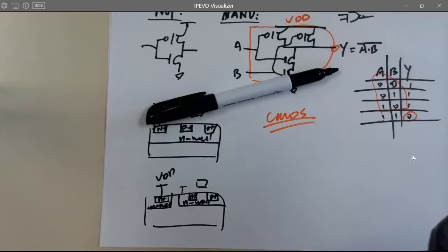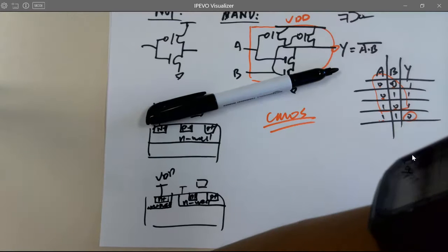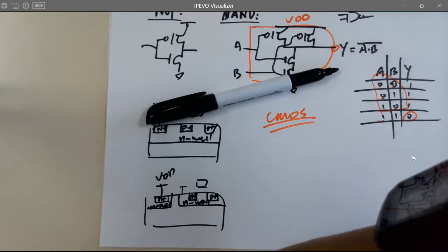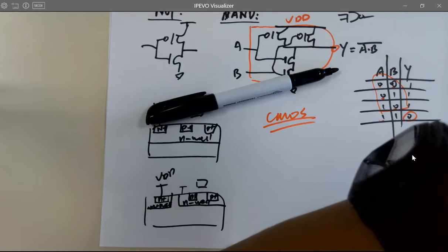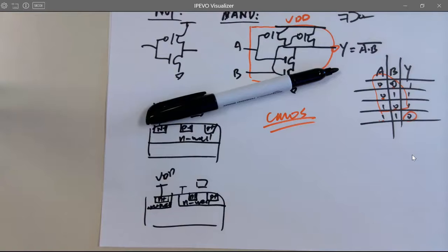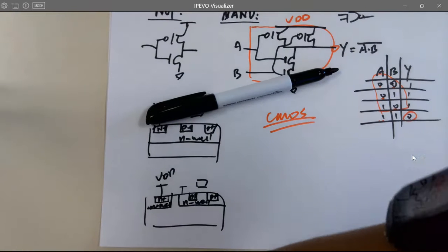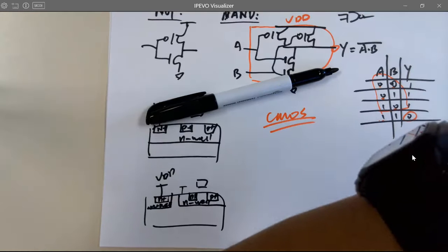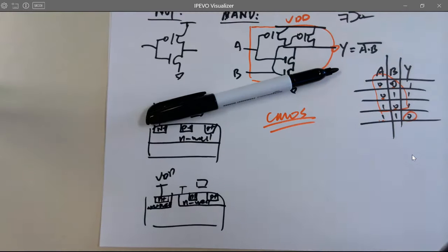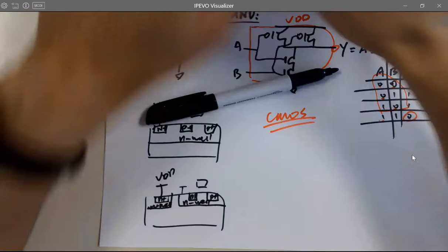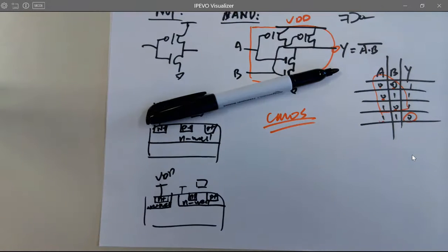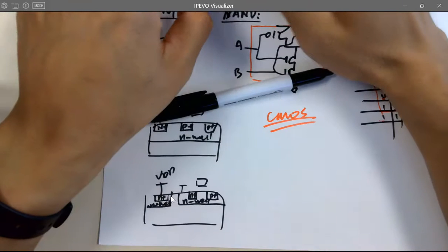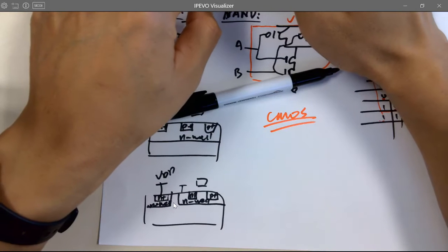The smallest size they can fabricate is 500, for example. And the size between the two wells is like only 1 nanometer. It won't pass, right? Because the tool or the foundry is thinking like, you really need a 1 nanometer gap. But actually you won't be able to. So actually they will be overlapped, but it's an error being seen as a foundry, right? That's a problem. So in order to avoid that issue, just directly draw a huge box to cover everything and put all the PMOSes and N well contacts in the same N well.